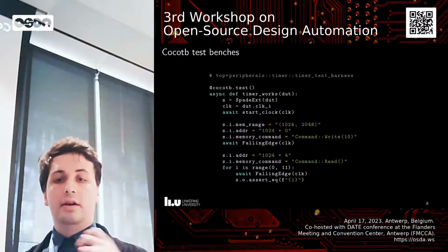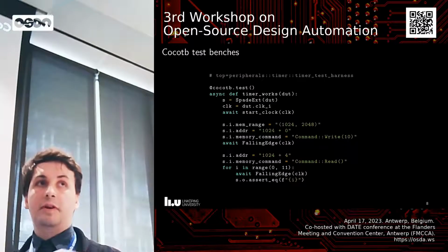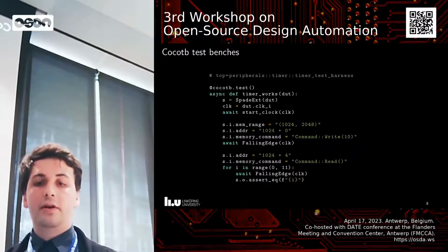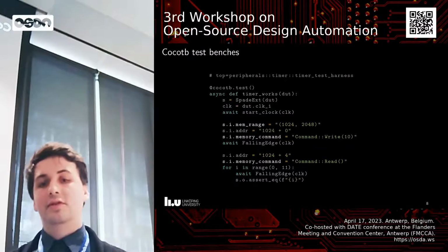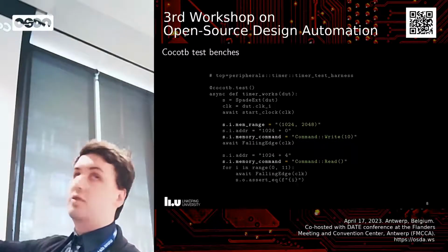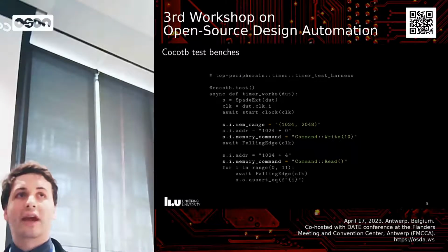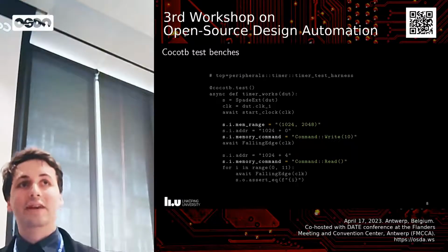We have test benches in cocotb, and cocotb is a Python testing framework for Verilog. The thing that Spade adds to it is the ability to write Spade code inside cocotb. So you can write a string with a Spade expression, it goes out to the compiler, compiles it, and that way you don't have to care how the compiler decided to encode your enum or your struct.